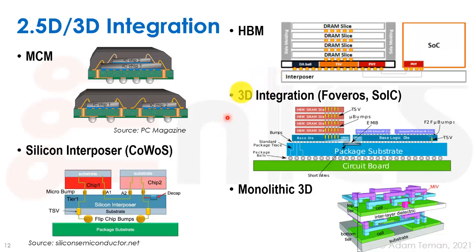Some other things that we have are HBM. That's the high bandwidth memory. That's one of the types of DRAM approaches that has been used for 3D integration. And you can see something like this. So we have one of these silicon interposers similar to what we have over here, right? We'll put our SoC or whatever our main product is going to be on top of it, and it's going to connect to just DRAM through the silicon interposer, to get nice short bonds to it.